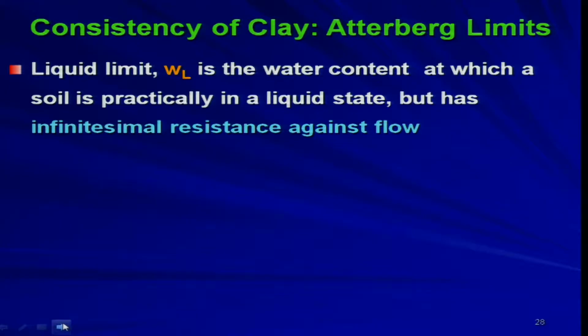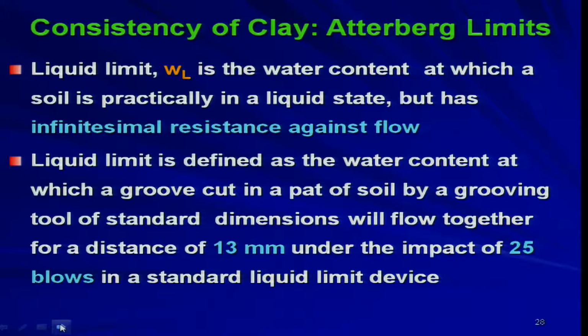It is generally represented as WL and it is defined as the water content at which a soil is practically in a liquid state, but has infinitesimally small resistance against flow. So, basically you do not have any resistance to the flow. Liquid limit is defined as the water content at which a groove cut in a pad. So, this is again related to your laboratory experiment.